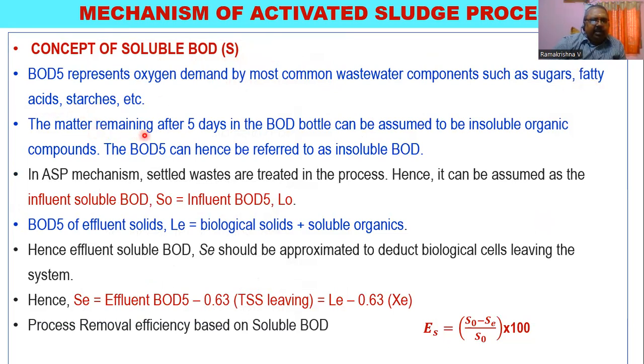The matter remaining after 5 days in the BOD bottle can be assumed to be insoluble. Whatever soluble material is there has already undergone decomposition during the first 5 days. That's what we are calculating in terms of BOD5. So that's why BOD5 can hence be referred to as insoluble BOD.